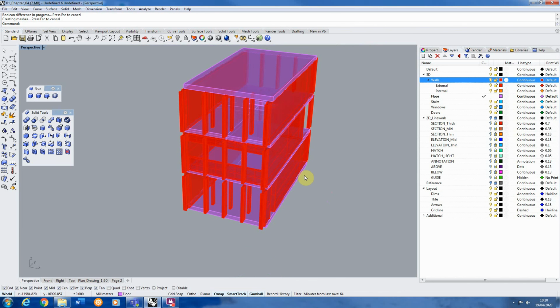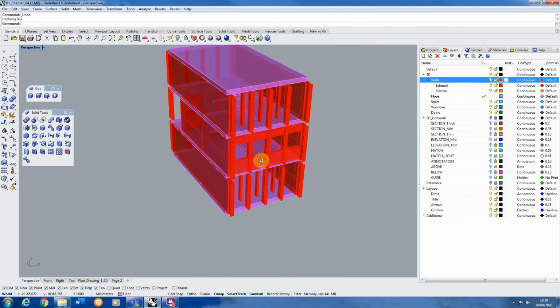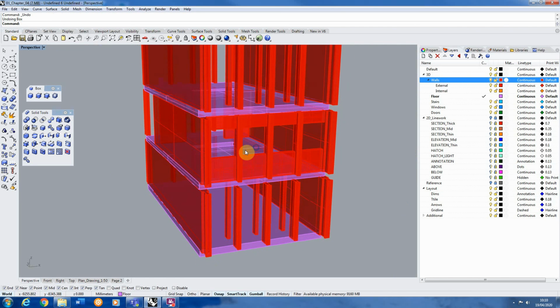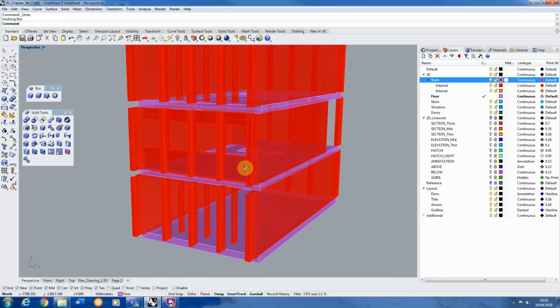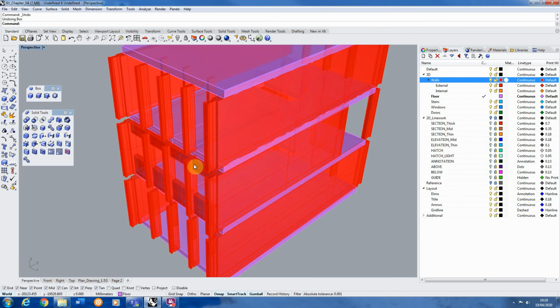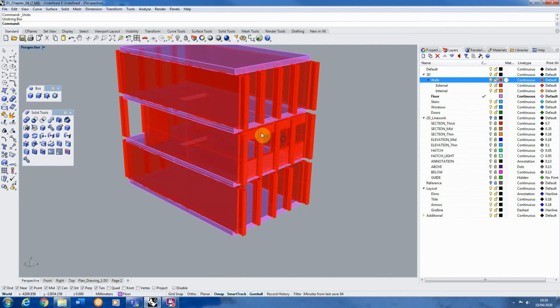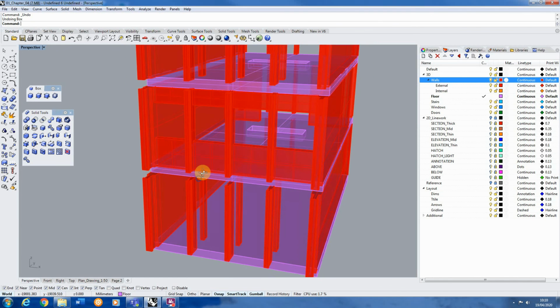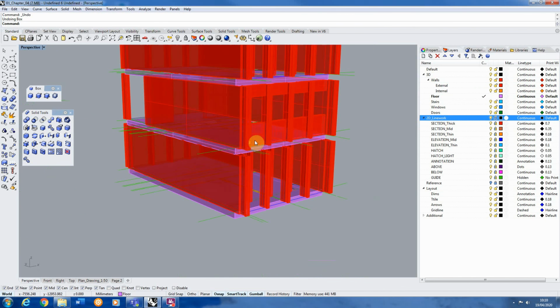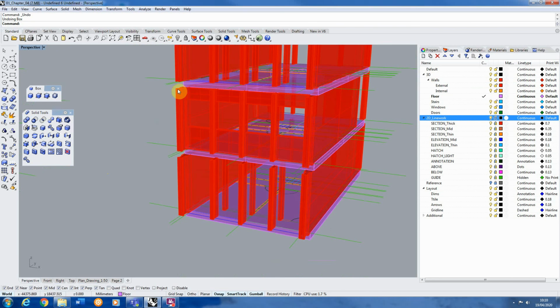Now we're going to stop this session here because that was all we needed to cover for this first stage. We've basically looked at setting up your 3D model space with your layers, rotating and moving your plans into place so you can start to extrude from them, and then we've looked at extruding walls up and subtracting and adding shapes to one another using the Boolean difference tools. So I'm going to now extrude up both the internal walls on my plan as well, so they match with this, and start to put in all my window sills using the Boolean Union tool and Boolean Difference tool to cut any extra holes I need.